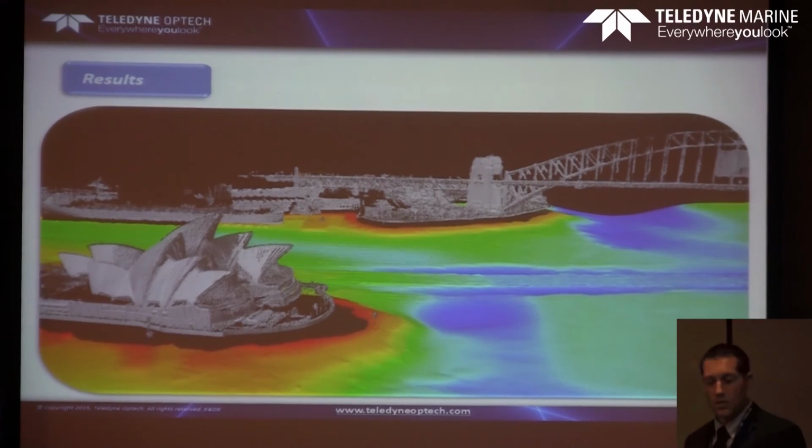So what can you do? There are different ways to do it. You can play with the tide, so whenever there's low tide or high tide, you can survey the missing points, or you can actually tilt the sensor head, the multi-beam, by 30 degrees, and you get this data set. And this is what we did in the next slide.